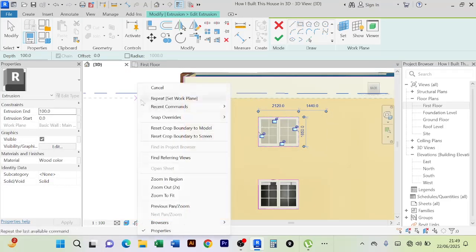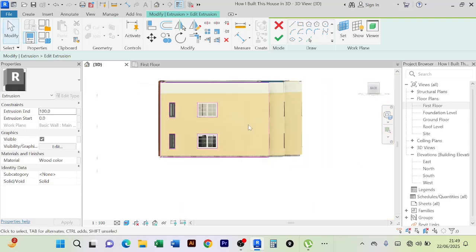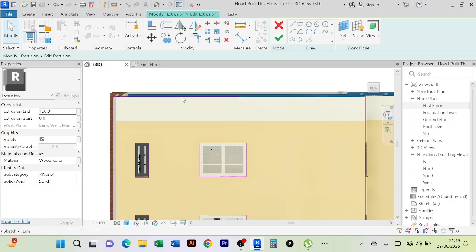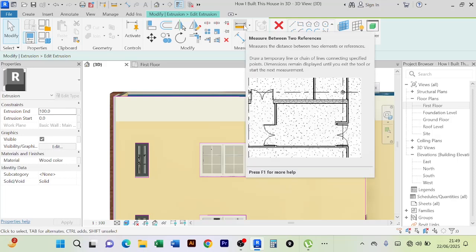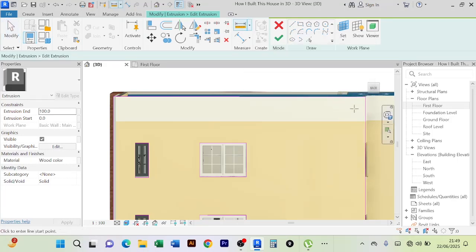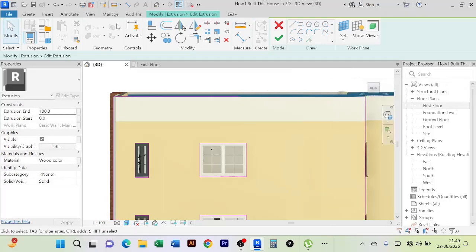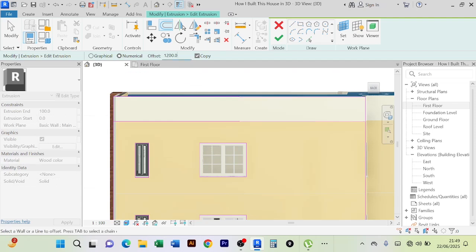Now, after picking these ones out, I want to create another thing. We shall be creating a lot of different kinds of designs, but of course with time you can use them for your specific projects. So we're going to offset this side. Let me first measure. There's also this measure tool which you can use to measure from one point to another. This is 1.2. So I'm going to offset 1.2, just like that. I'll offset 1.2, then I'll leave a gap of let's say 20